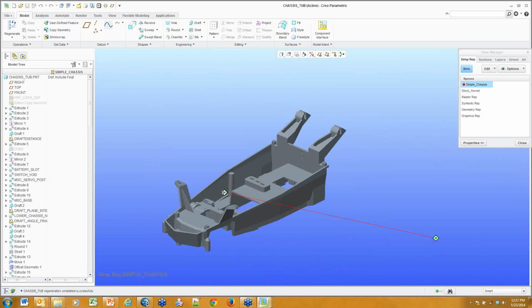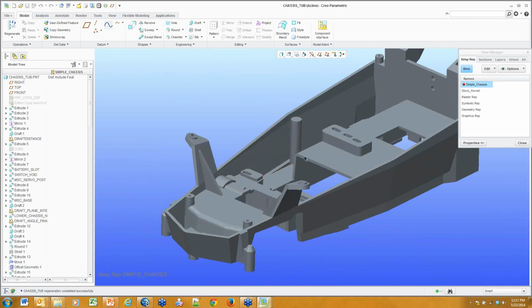Okay. This means when we mesh the model, it will mesh much quicker since it doesn't have to focus on a tremendous amount of rounds. On top of that, due to the curvature of some of these rounds, you may get geometry that you are not able to even mesh. So trimming down the model features that we don't need is going to make the model run the simulation quicker and even allow a complex model to be meshed that maybe wasn't meshable before.